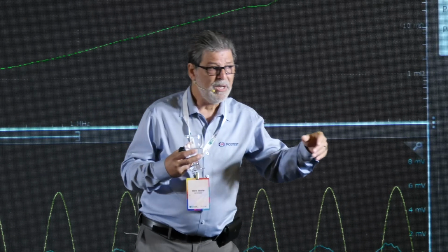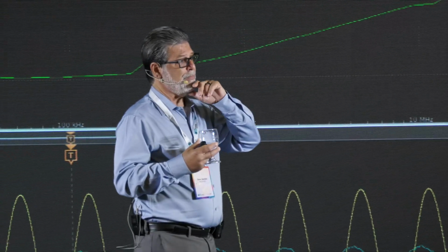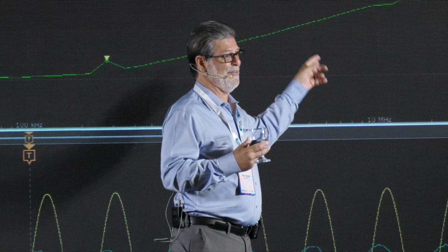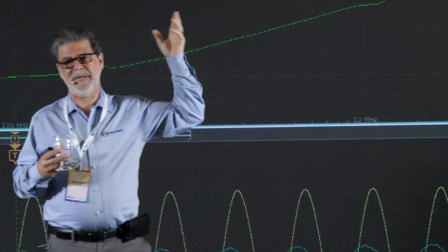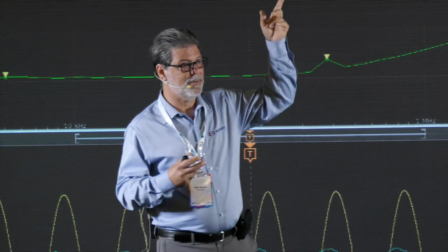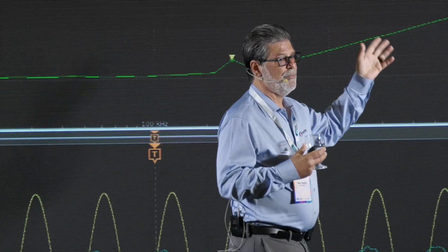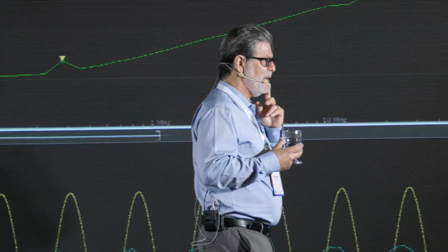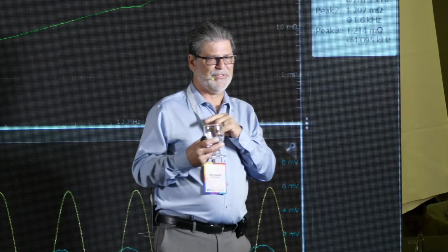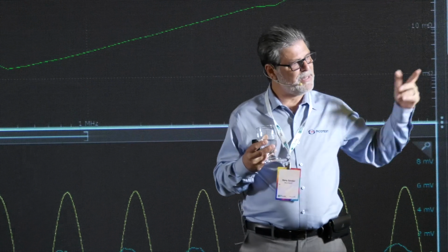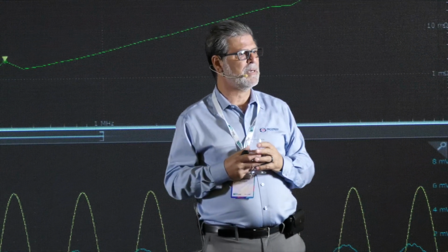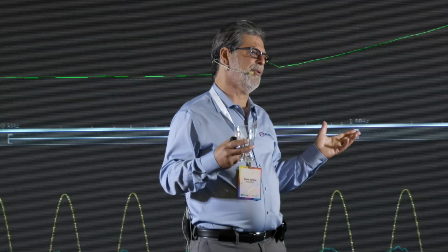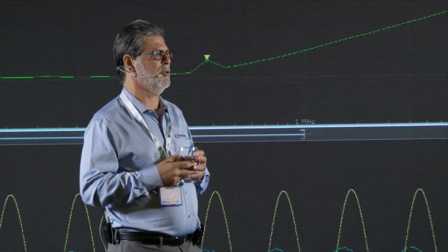How much of the voltage that you're looking at in the power rail is going to come from switching ripple? Tomorrow, if you're in my paper, I'm going to show you something called jitter-induced jitter, a power integrity problem that comes from jitter of the switching frequency of the VRM. I worked on the GPS navigational clocks. There's 4 clocks in every GPS satellite, 3 rubidium clocks and a cesium clock, and they had trouble with the rubidium clocks. The problem that they had with the rubidium clock was the 1530-second harmonic of the switching power supply that got into the phase lock loop of the clock. And so would a resistor network show me that I had a 1530-second harmonic that was getting into a phase lock loop? Of course not.